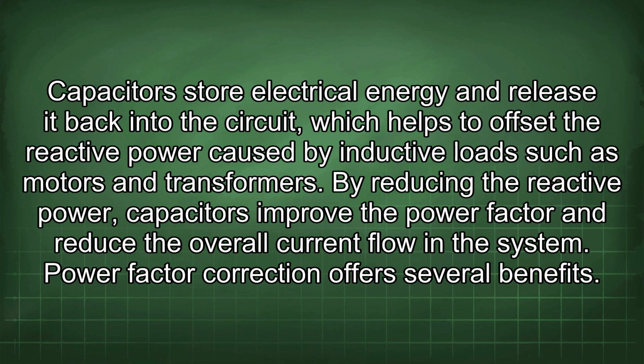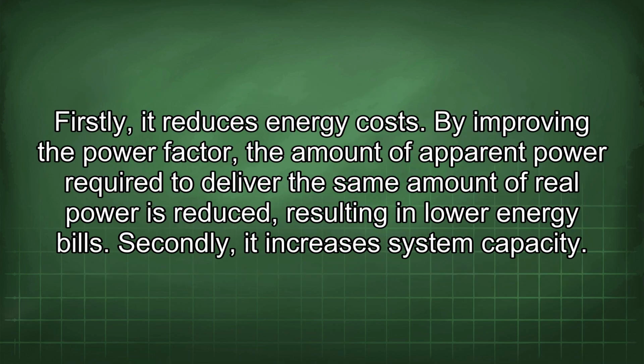Power factor correction offers several benefits. Firstly, it reduces energy costs. By improving the power factor, the amount of apparent power required to deliver the same amount of real power is reduced, resulting in lower energy bills. Secondly, it increases system capacity.